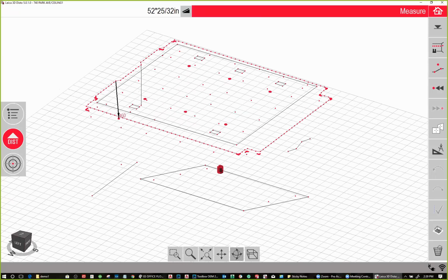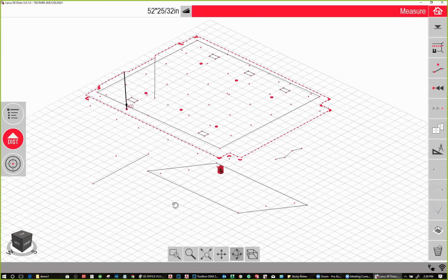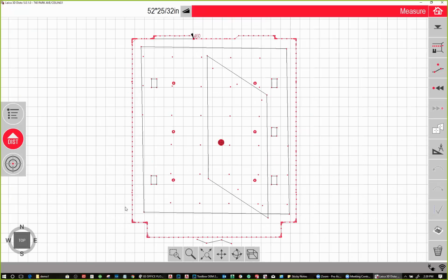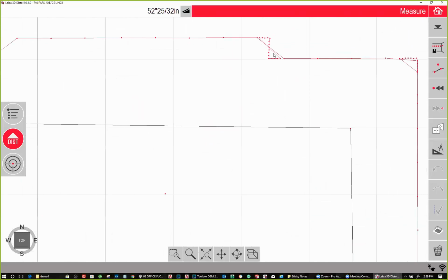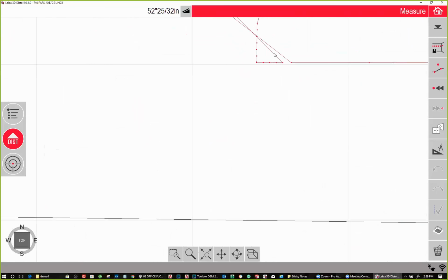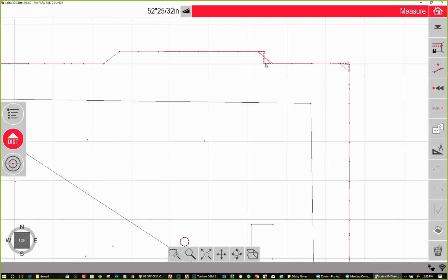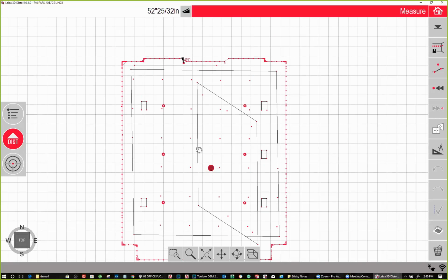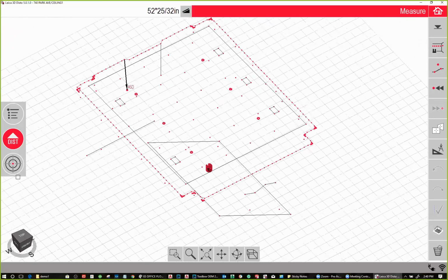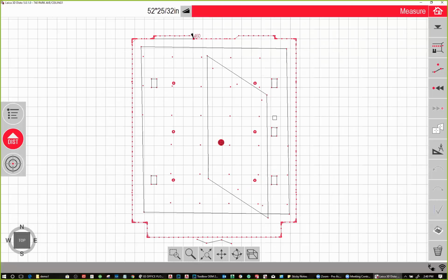So what I did was I captured the perimeter. So I kind of have the perimeter, and there's some parts in here where I did an auto scan, and for time's sake, at the job, I didn't clean it up, and I went back and cleaned it up in AutoCAD later or Microvellum later. But I captured the perimeter, and then these squares were speakers that were in the ceiling. All the circles were lights that were in the ceiling.